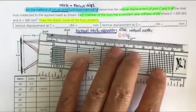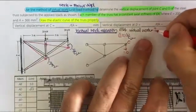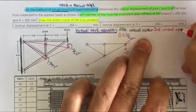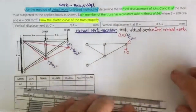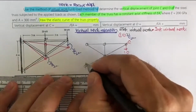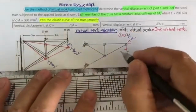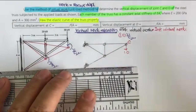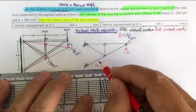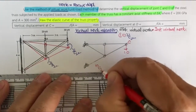This external virtual work must be equal to the internal virtual work. What is the internal virtual work? This 1.0 unit force, when applied to the truss, produces the member force called N sub CV.